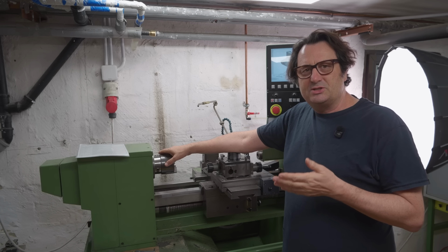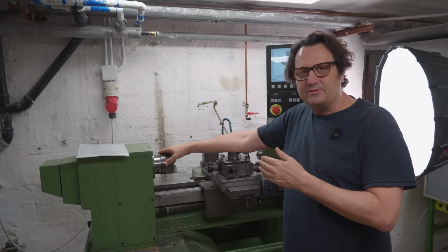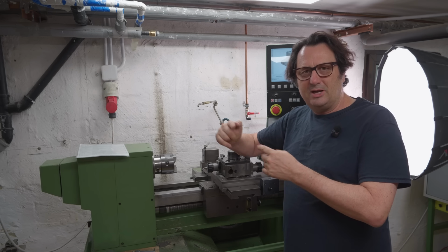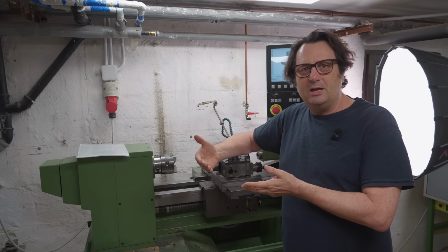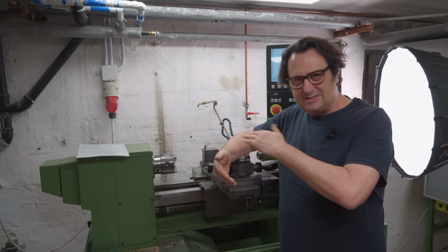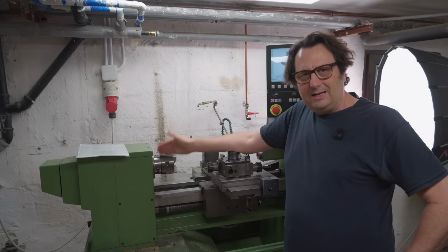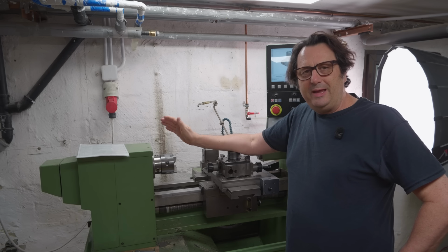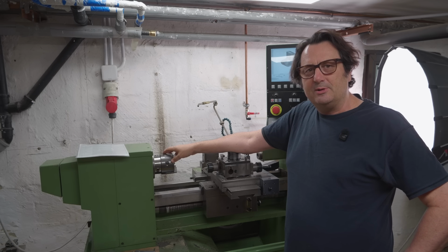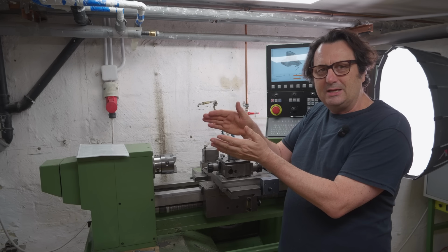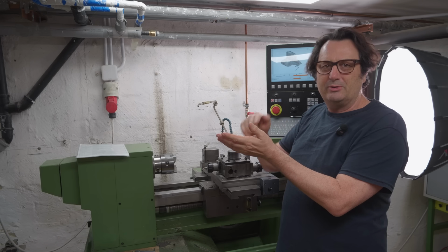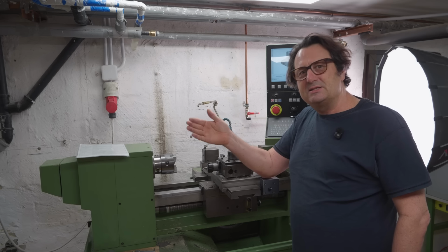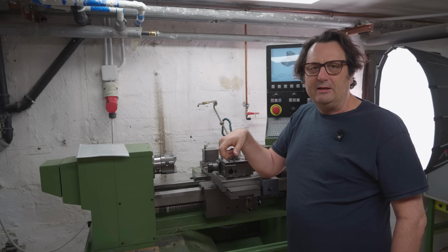I've got a motor at speed pin which outputs from the VFD. So I'm using that to inhibit the system calculating the gear ratio. Anytime that inhibit opens, so anytime we're at constant steady state speed for more than a second, I let the software calculate the gear reduction ratio and compare it to what it thinks it's at from the lookup table. And if there's a significant discrepancy, I don't try and do a closed loop, regulate back to the correct position. I just tell it to add or subtract time to the next CVT bump to try and correct the error.